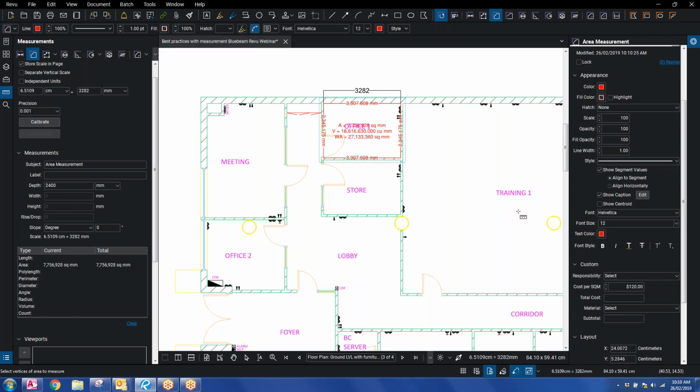If you are wondering what I mean by wall area and how you actually get that value, basically it is the height of the room that you can input by yourself. This is a 2D drawing, you can't see the height, but that's okay. If you know the information, you can put it in Bluebeam Review and it will calculate it for you as well. So where do you put it in? It is on your measurement toolbar here, which says depth. From here, you can change what the height of your room is. Say 2.4 is perfect for me.